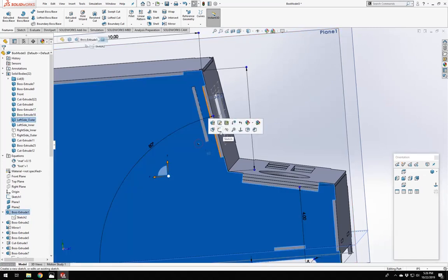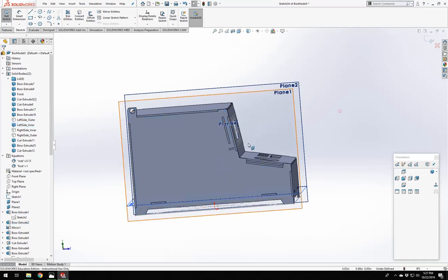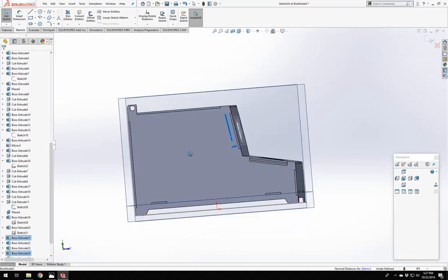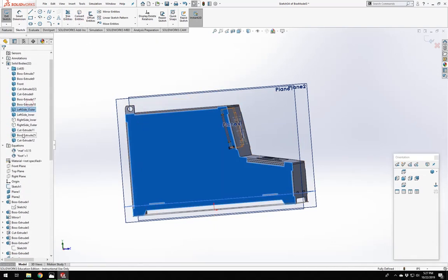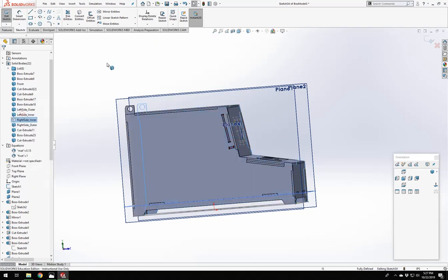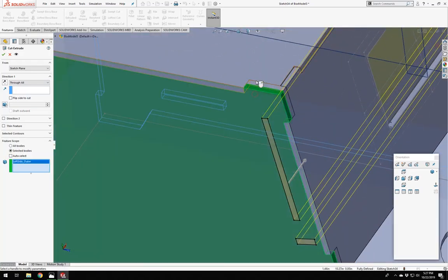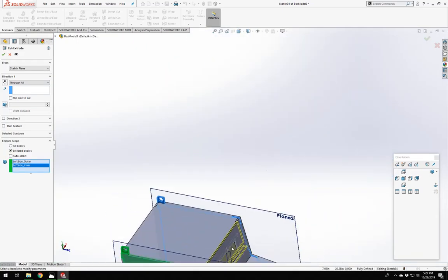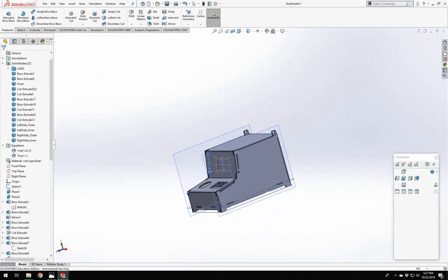All right, so we're going to put in the holes for those two pieces on this side. So again, sketching on the face. Easily just grab that and that. Convert entities. Bring out our left side and our right side. Do an extrude cut for both of these through all. Make sure we clearly define our scope, being those two, and those two. Missed one. There we go. So we now have the cuts for that.